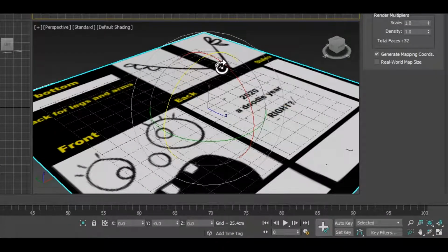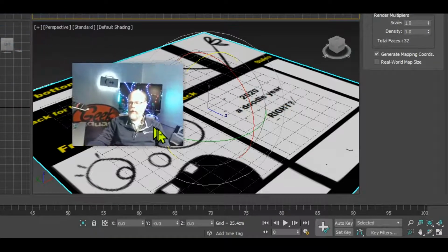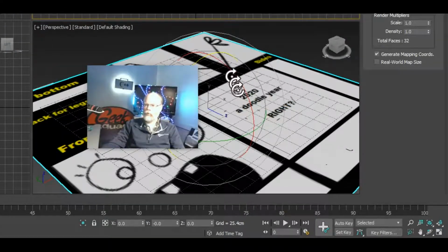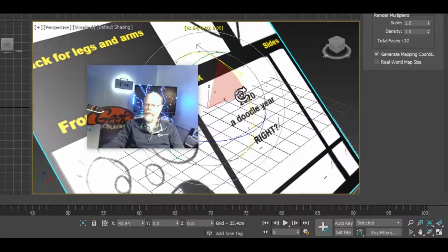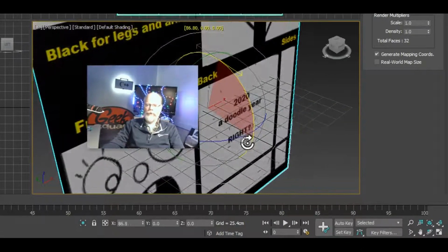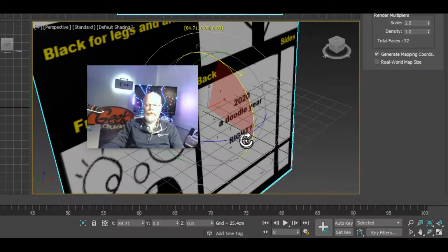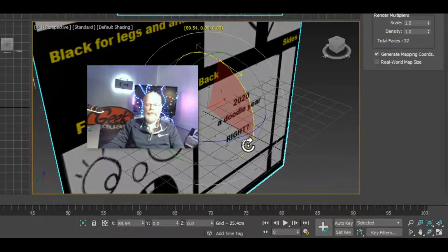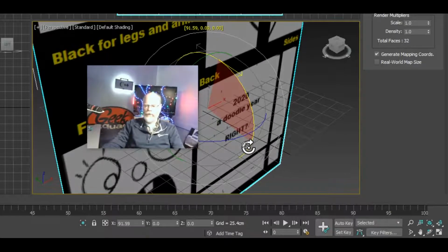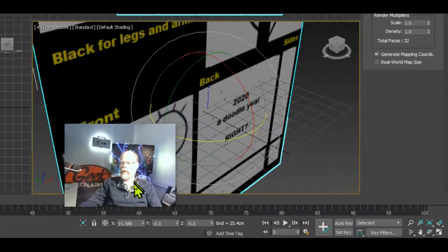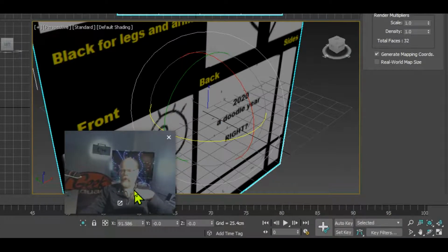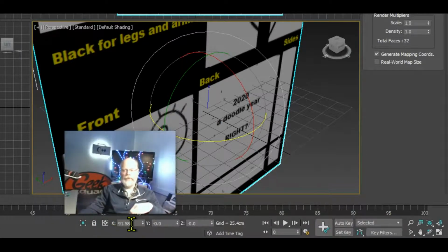And since I'm in the rotate mode, it is a mouse operation, and I'm going to pick on this red line here. And if I click and drag on it, you'll start to see in all the viewports it's reflecting that I'm rotating my image. My goal is to get to 90. Now, it might be difficult to get to 90 as you're rotating it, especially remotely. So as a reminder, directly below where I've got myself as a cursor here, there's the number that reflects not the location in this instance, but the rotation.